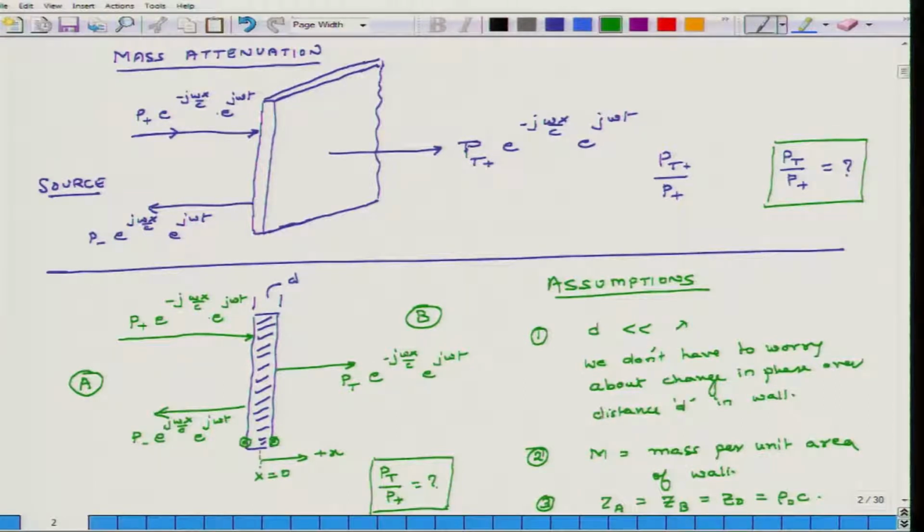Okay. And it is not 0 because the wall is free to move. So, when I put a partition between 2 rooms, if some pressure is being applied, unless the wall is rigid, but if the wall is free to move, then it can move back and forth, even though that displacement and velocity may be small, but it is free to move. So, whatever is the value of velocity on the left side of the wall is the same as velocity on the right side of the wall. So, that is our first boundary condition.